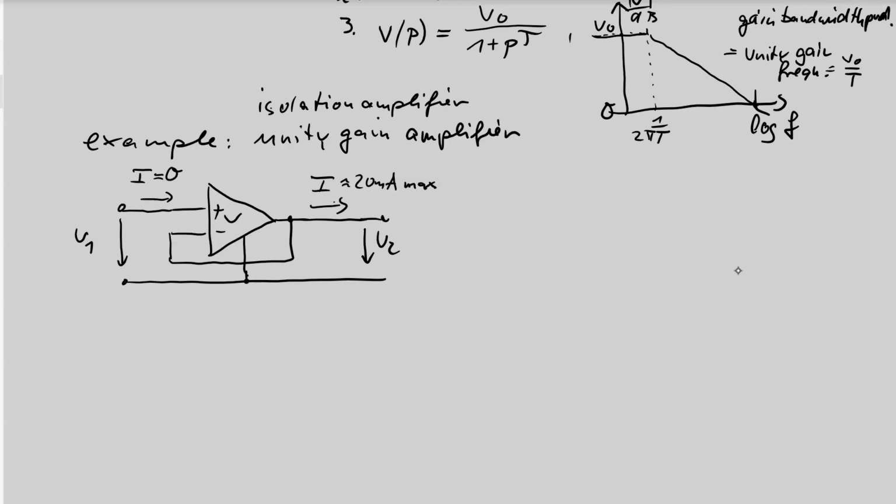Okay, signal block diagram, SBD. We need equations. The first equation is the operational amplifier equation: U2 is V times UD. So we have an internal unknown parameter, that is UD, so we need one additional equation. The equation should contain U1, and we go into a voltage loop.